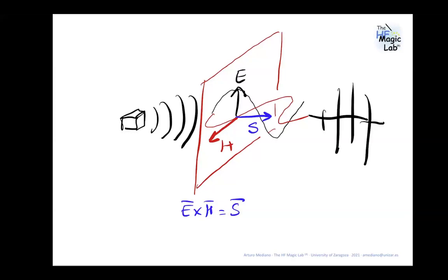RC snubber sometimes is impossible to avoid in flybacks, in the diode at the output of the flyback secondary, or in other switching activities. So it's not really that I recommend it. It is that in some applications it is mandatory, you know. But with a good layout, in the PC board I presented from MPS, I remember that there is no RC snubber and the emissions are minimum.